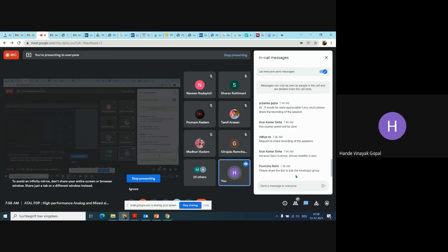In many circuits, people use level shifters because the external IC generally works at 5 volt, like communication ICs particularly. I don't remember the name exactly, but other communication ICs and digital ICs can work on 5 volt nowadays. So when I am working at 1.1 volt, I'll use the level shifter so that I can drive the 5 volt IC at the output.